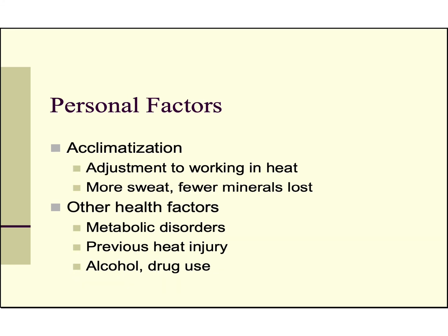The TLV is based on protecting most people, but we also have to consider personal factors when we consider the actual heat strain that may result from any given heat stress. We've already discussed acclimatization, which is adjustment to working in heat. The physiological effect of acclimatization is that a person will be able to sweat more, and the sweat will be more dilute, so they'll lose fewer minerals, less salt in their sweat, and so they'll be better able to work in heat.